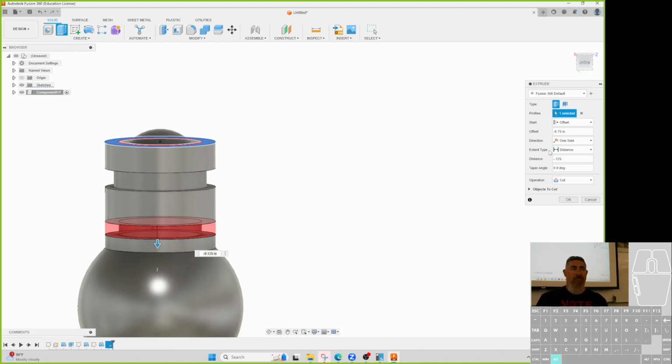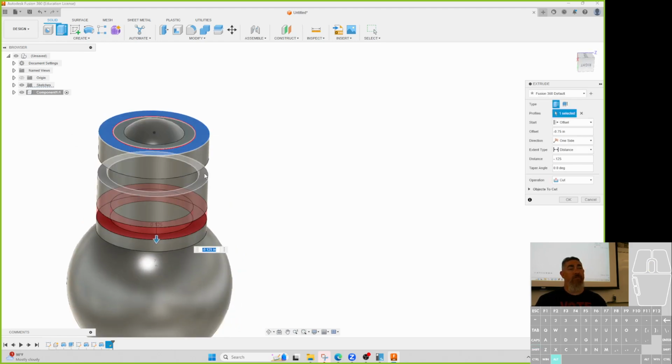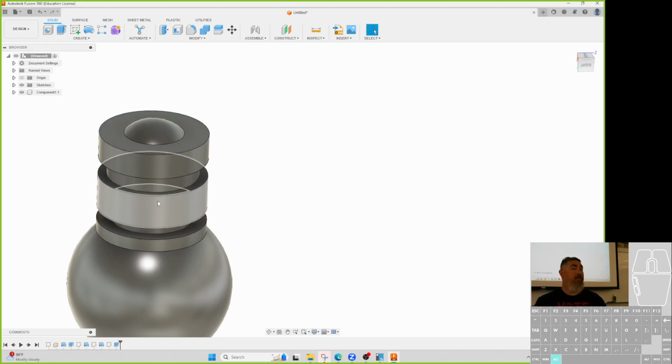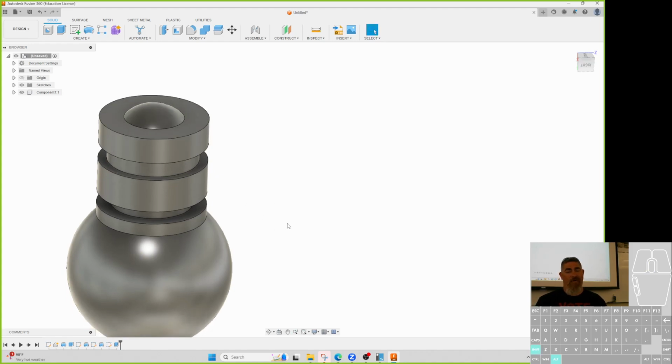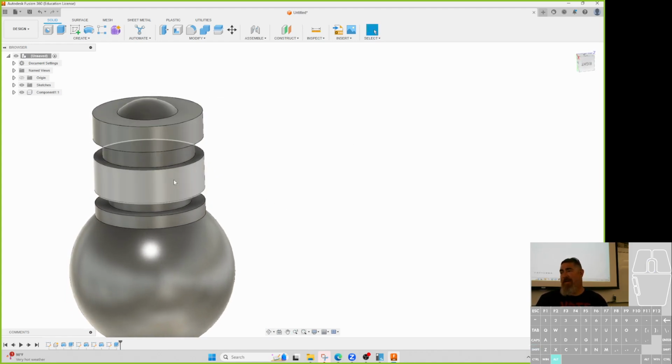But if you do it as a revolve, am I going to be mad? No. But it's just another option. Okay? And it also depends on what the dimensions are from and everything. But I'm trying to show you some different options on how to do things. And this is one that has been there, I think. Just I never did it this way. Did you do multiple extrudes from that one circle that you drew? No, I just did one. I had done this one as a revolve. What if they wanted another ring like that? Then I could do a pattern of it. So either one, I would just do a pattern of whatever. So it gives me the same thing, just two different ways to do it. They're both okay. I'm not super mad about either one.